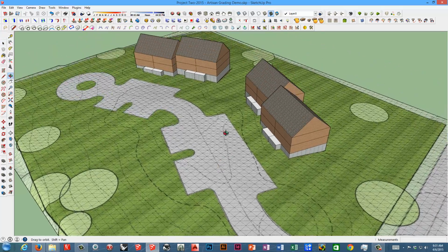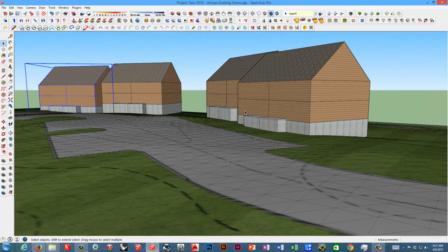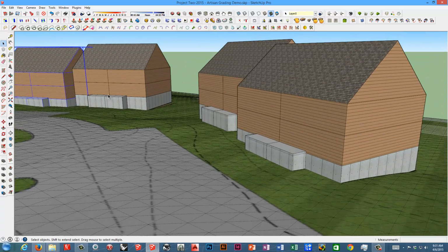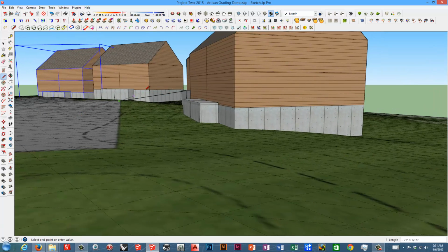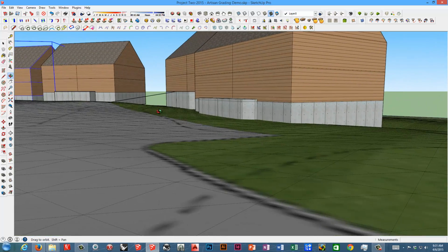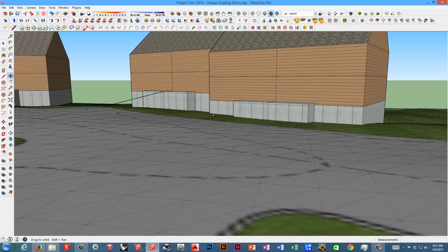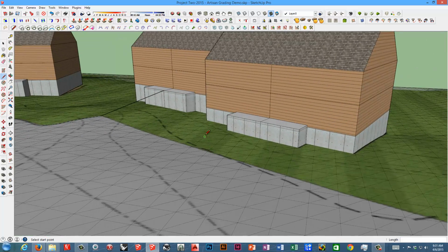And so basically then I brought in the buildings, I modeled those, and they're each created as a separate block, so I can move those up and down. And I've already kind of placed them. I think they have 2 feet between the upper unit and the lower unit on each side. I kind of just drop them into place and then move them up and down to eyeball that. But you can also just take a pencil line and come in here and snap back to there and start seeing what the elevation is. And again, this isn't perfectly accurate. I'm not setting these finished floors at a specific elevation. I'm just doing this to work out a rough grading plan very quickly to understand what's going on with this site.